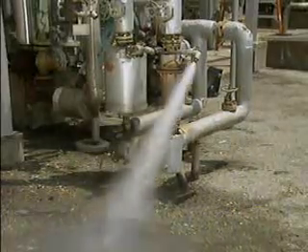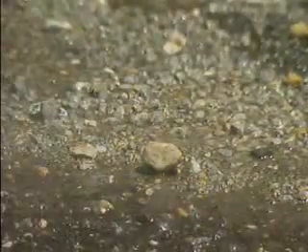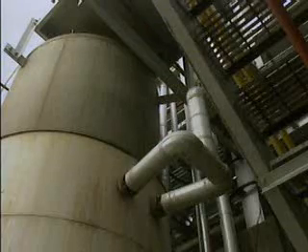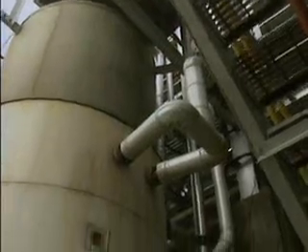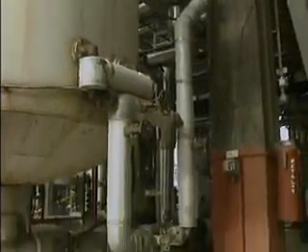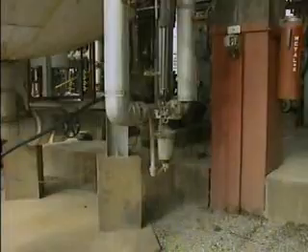Steam is a vapor that's formed from water. The condensate that's formed as steam cools is a liquid that's heavier than the steam. In a steam system, the relatively heavy condensate will drain to the system's low points. So steam traps are usually installed at these locations to remove the condensate. Removing the condensate is important because accumulated condensate in a steam system can cause a number of problems.